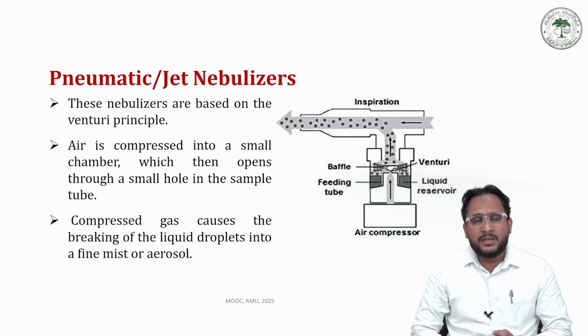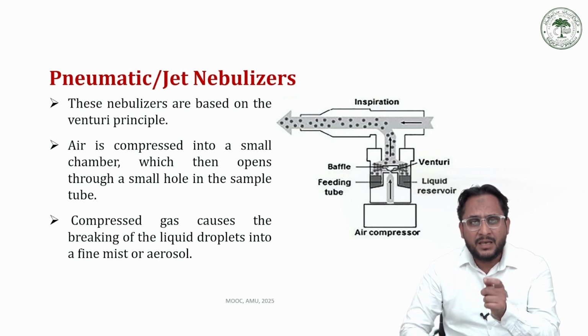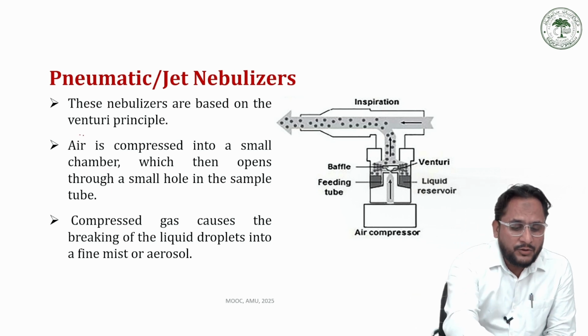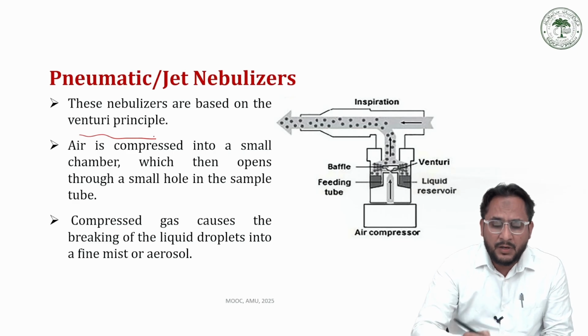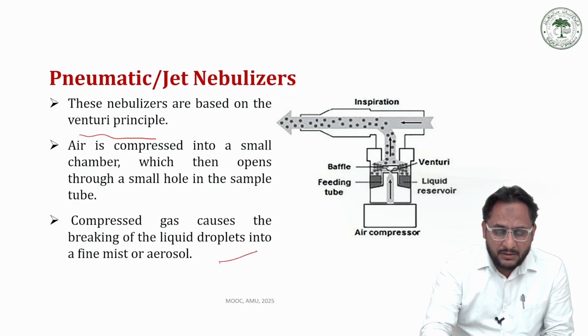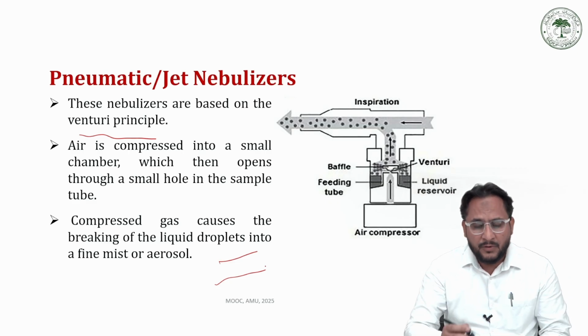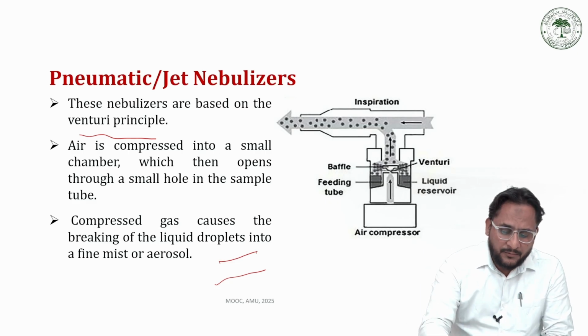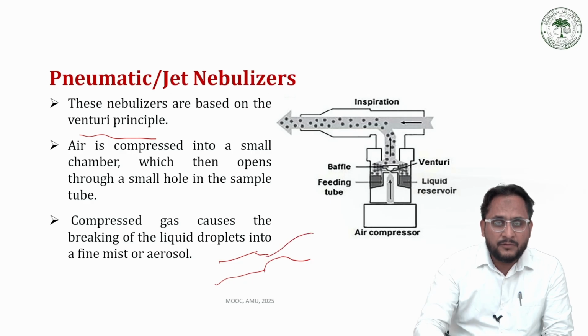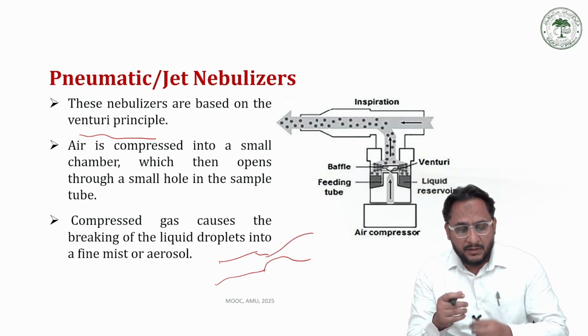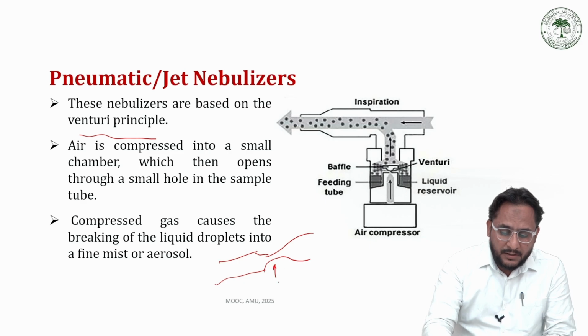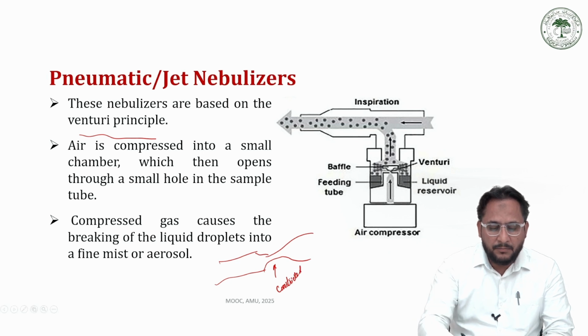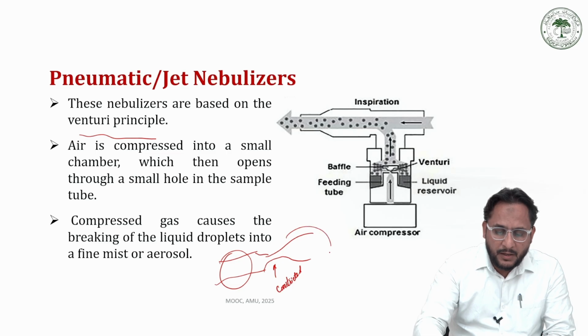Let us discuss the pneumatic or jet nebulizers. These nebulizers are pressure based, and they utilize the Venturi principle, which says that if a fluid, which may be a gas or a liquid, is flowing in a tube and the diameter of the tube decreases at some point, for example at this point, where you can see the diameter is quite constricted or lower as compared to the other parts like these two parts,